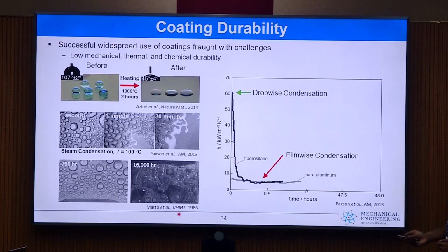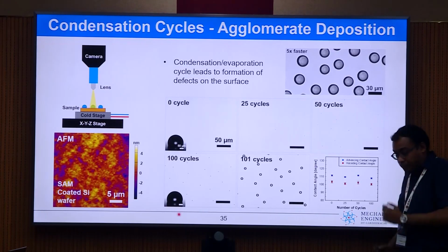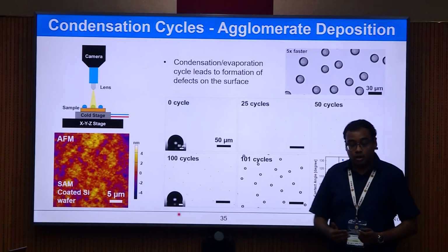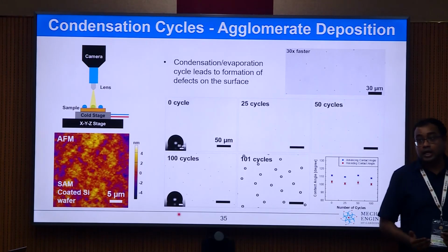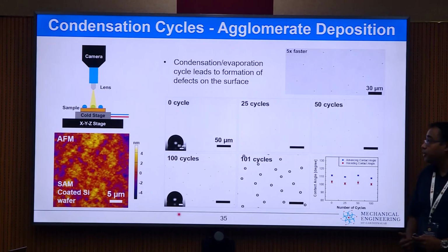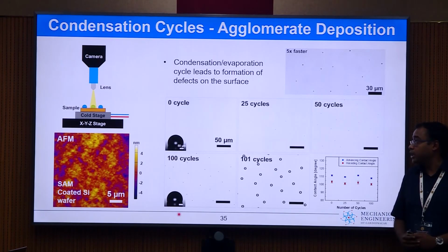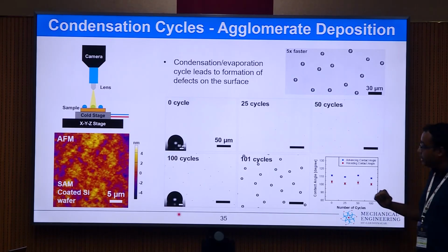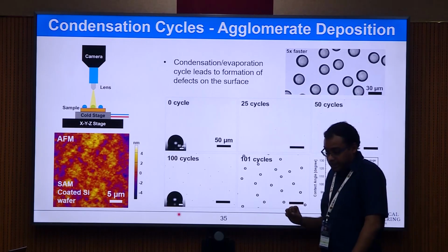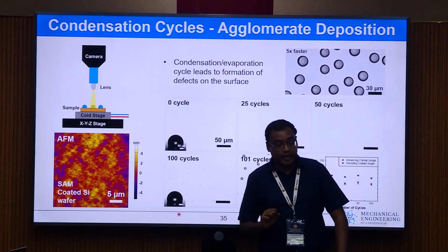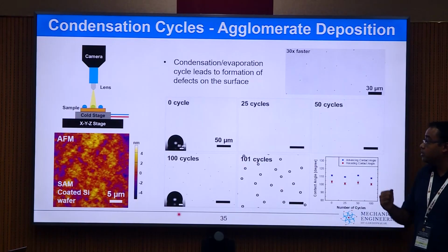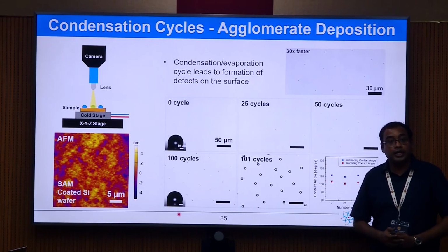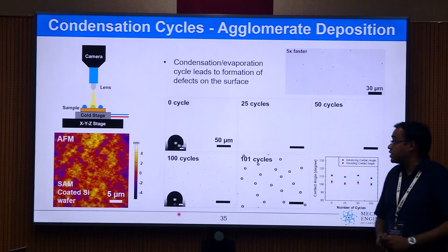Now, on one hand, it can be that the coating, or the engineered surface structures, are getting eroded. That is the cause of the failure, or the cause why the wettability is lost. However, in most cases, possibly it is not the surface that is degrading, it is the absorption of some molecules or contaminants which is creating this degradation on the surface.